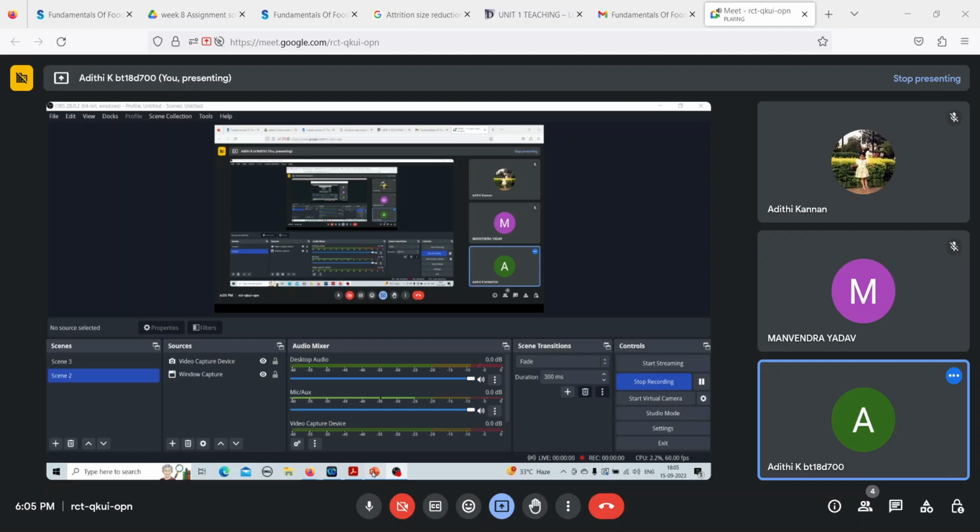So I am just substituting the values here. We already have all the parameters that are required to calculate the Nc. So 1 by 2 pi root of 9.81 meter per second square divided by capital R as 0.75 meters minus small r as 0.025 meters.